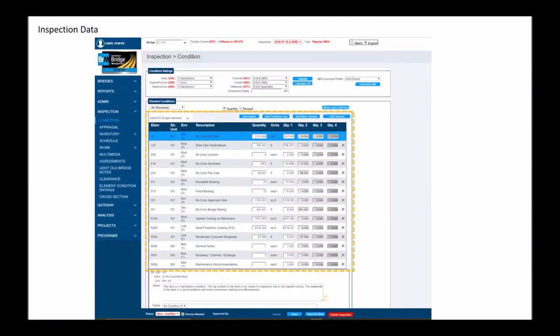We also previously discussed the 4 condition states, also defined in the AASHTO manual. Just to recap, condition state 1 is the quantity in good condition, condition state 2 is fair, 3 is deteriorated, and 4 is poor or missing condition. Inspectors on site during their inspections input how much quantity of each element is in each condition state, and this inspection data is the foundation for all the optimization work that we will be doing in future.